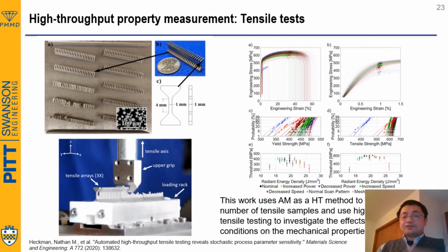So this is a kind of tensile testing. I find this is also very interesting work, because the people who worked on this are using 3D printing to print a series of mini-scale tensile bars. And then they pull the tensile bars in an array like this, and then they can evaluate the strength of the material. That's fantastic in the future if we can really have such a setup utilized for designing additive manufacturing samples.